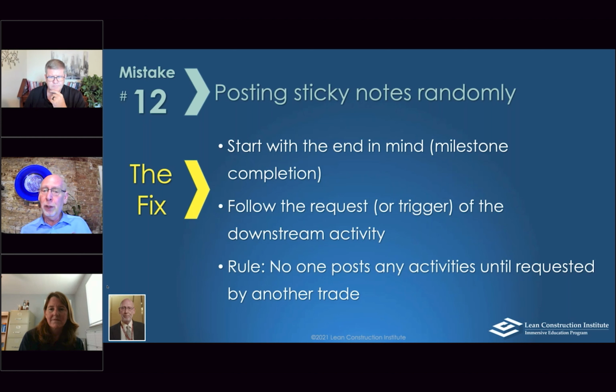So we understand that pull planning, as we've been describing it, is actually a radical change from the standard Gantt chart critical path method of planning, right? We are planning from the end, not from the beginning. We move backwards and see where the commitment chain gets created, and then we work off of that. And we do go back and forth. People say we just go backwards, that's a mistake too. We start backwards to do a preliminary layout as far as sequencing of work is concerned.